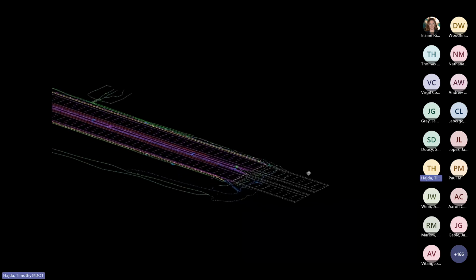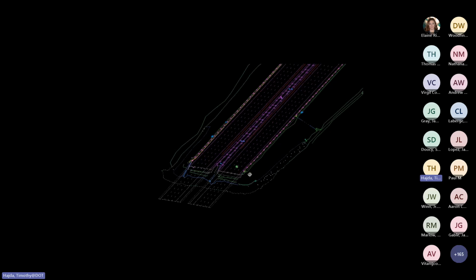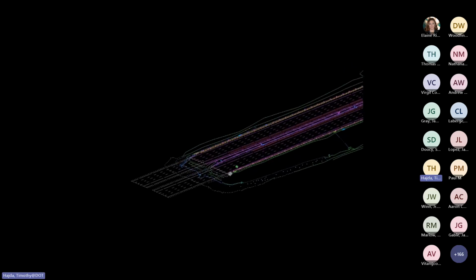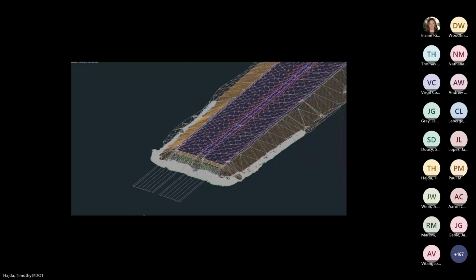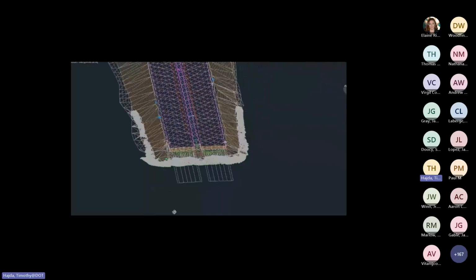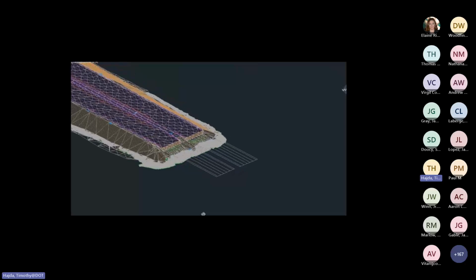So combining all 3 of those point clouds from the mobile scan, stationary scan, and the drone flight, our office staff extracted the roadway, bridge decks, soffit, original ground, and the boulders that I just mentioned for the design data survey. Here we are with the triangles and the contours displayed for the final surface in Civil 3D.